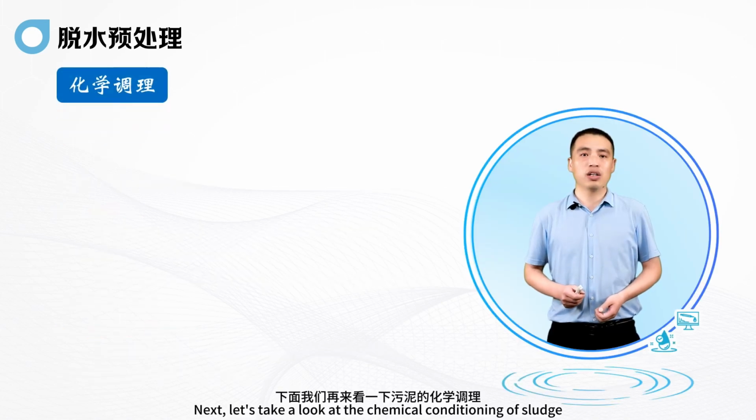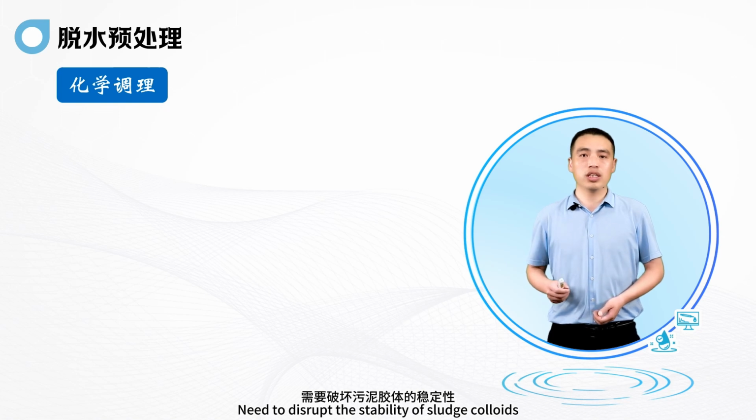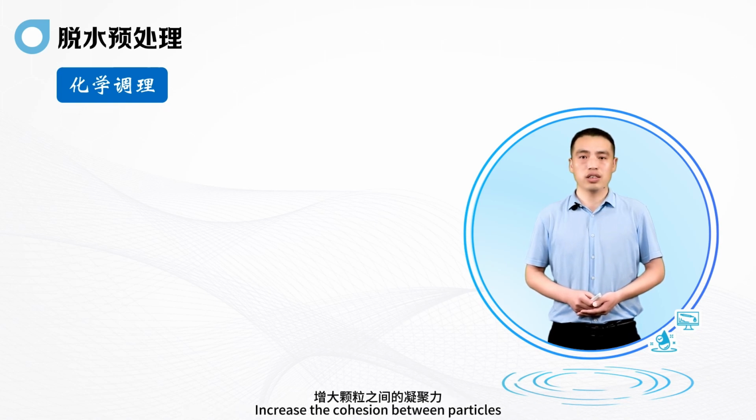Next, let's take a look at the chemical conditioning of sludge. The solid particles that make up sludge are generally very small and carry a negative charge, forming a stable colloidal suspension. Separating solids from water in sludge is therefore difficult, as it is hard to concentrate and dewater. To solve this problem, we need to disrupt the stability of sludge colloids. So the purpose of chemical conditioning is to utilize the charge carried by the agent's composite particles to reduce the affinity between solid particles and water molecules, increase the cohesion between particles, and increase particle size.